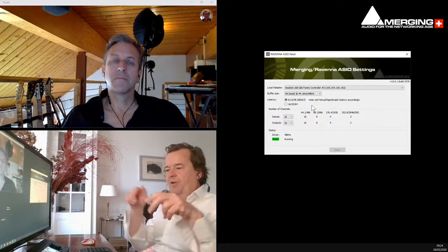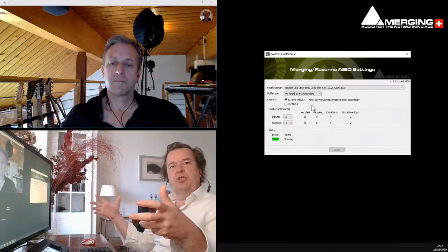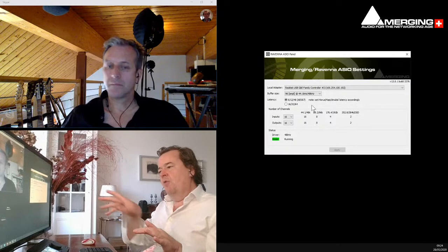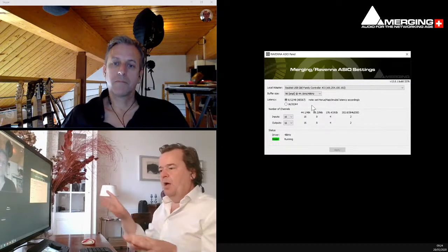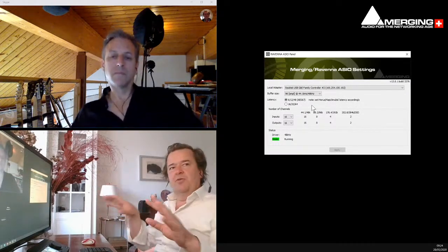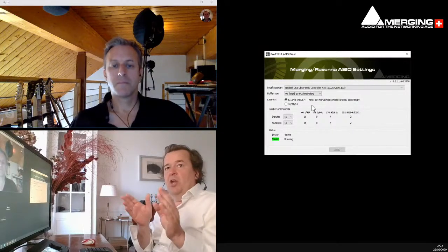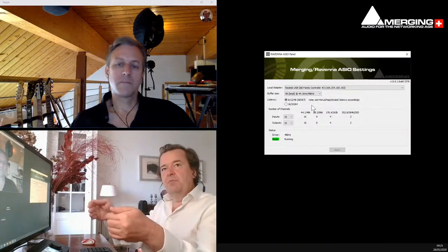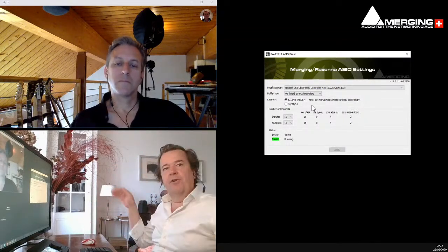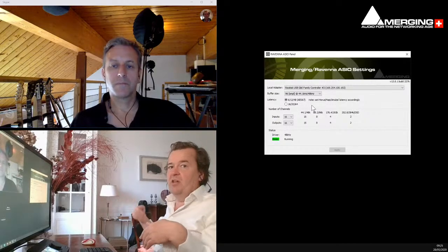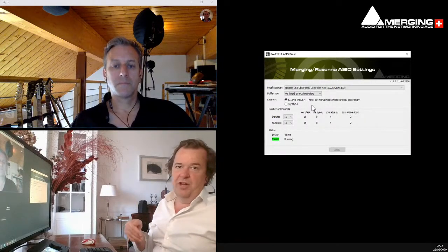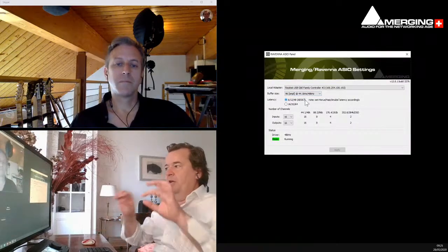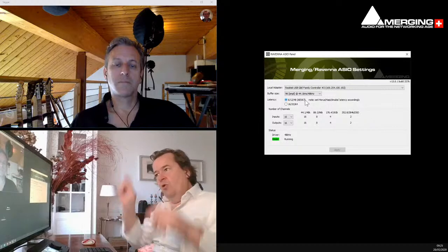So that means that if I have one big machine feeding multi-channel over the network, obviously some of those channels will take this path, some other ones this path, and so on. So that the latency of all those packets going through the network is such that they arrive at the same time, so that we don't have variation, where channel 23 is delayed compared to all the other channels, which you obviously don't want. This is why we have to have a fixed latency, which is the same, I insist on that, on all the devices.